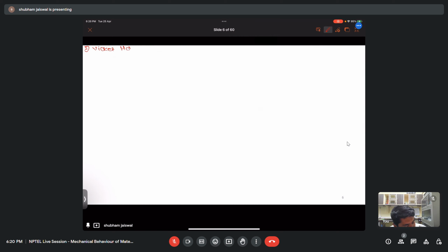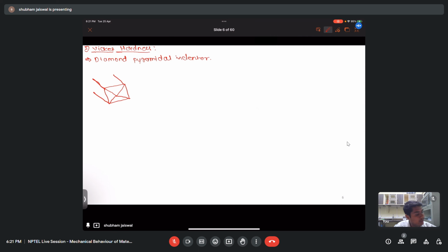Okay. So now after this, we have seen the second method, that is the Vickers hardness. So in Vickers hardness, we use a diamond pyramidal indenter. Okay, so let's say this is my diamond pyramidal indenter.